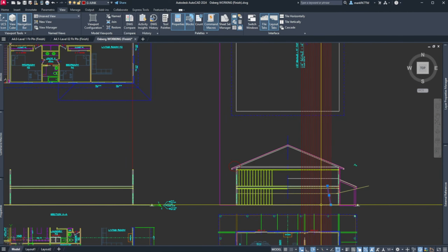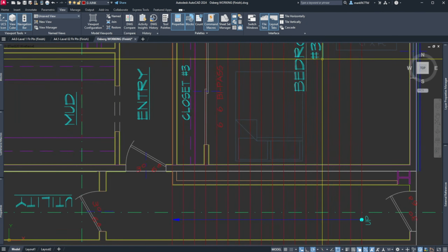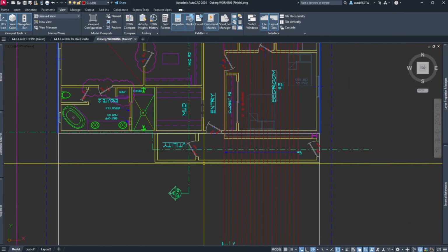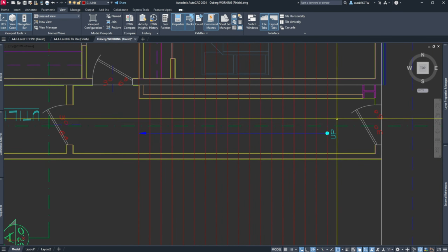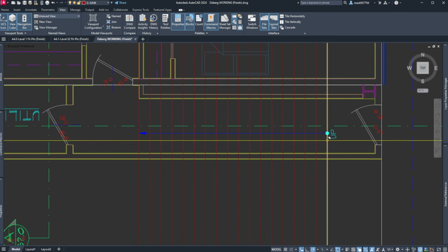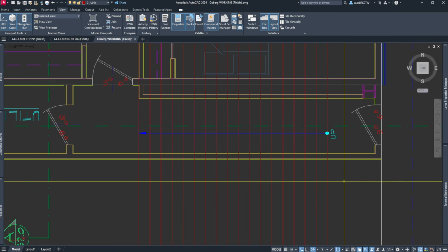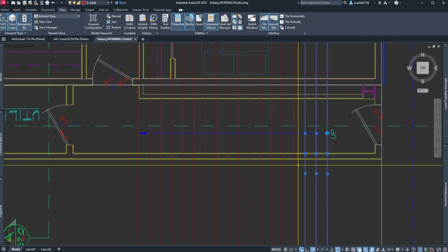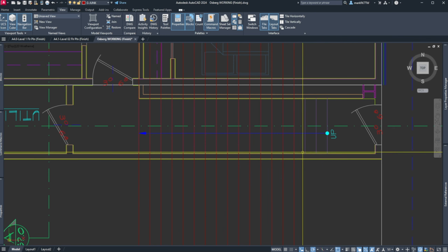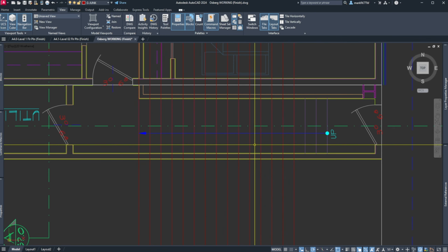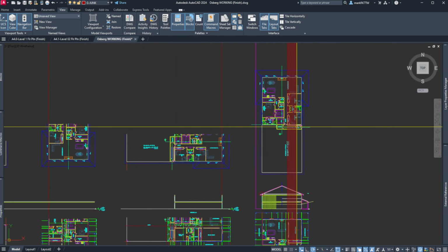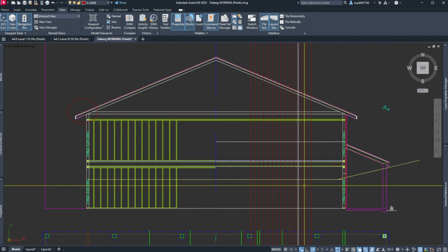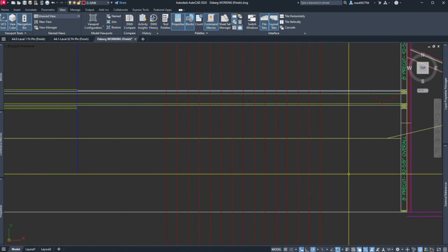And if I wanted to come and look, where would I want that to happen? This hallway looks pretty good. Having a little extra room down here doesn't sound like a bad idea. So I had 18 and I need 15. So let's get rid of 3. Now let's check it again. 1, 2, 3, 4, 5, 6, 7, 8, 9, 10, 11, 12, 13, 14, 15. So there's my 15 risers. So this is my distance that I've got to make this happen in.